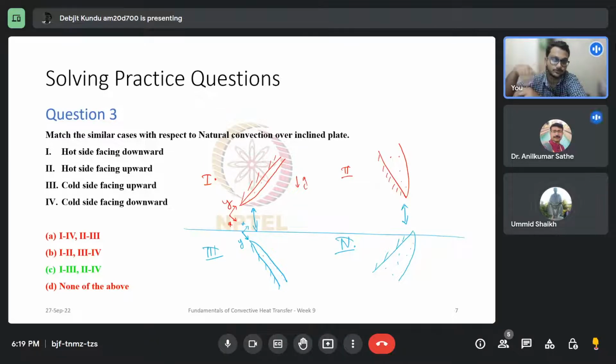In 2, it would be from the solid to the fluid, and reverse for case 4. Not only those average quantities, but even the velocity profiles and temperature profiles will also be the same, given that you keep those non-dimensional parameters the same and the scales also the same. Right. Okay.